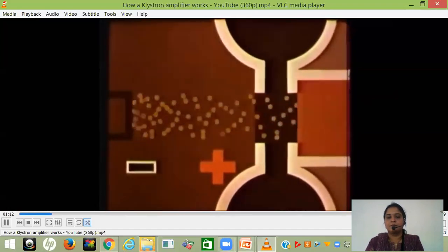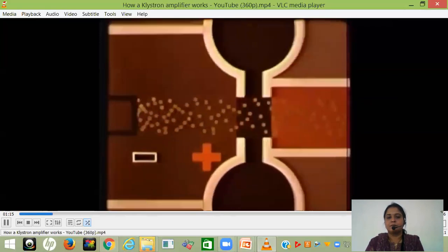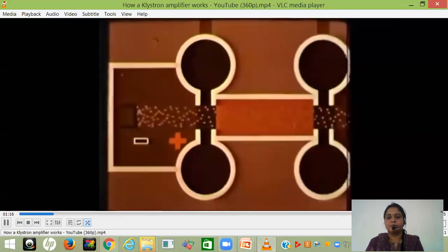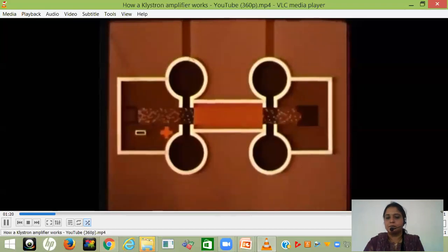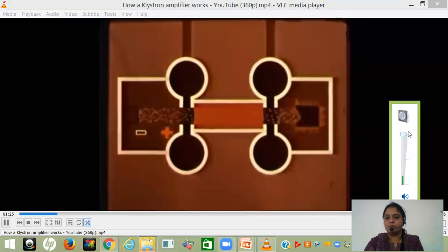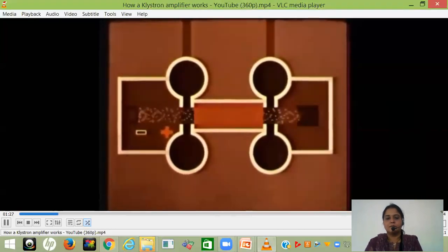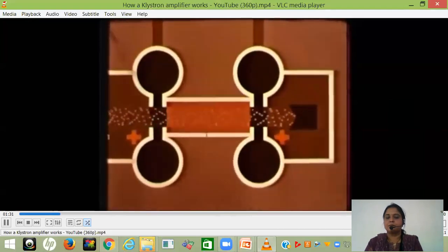Because the resonators have apertures in the form of grids, the electrons will continue until they reach the collector, which is at the same potential as the resonators. Therefore, in the region between the first resonator and the collector, the electrons would have a constant speed if it were not for the influence of the cavity resonators.